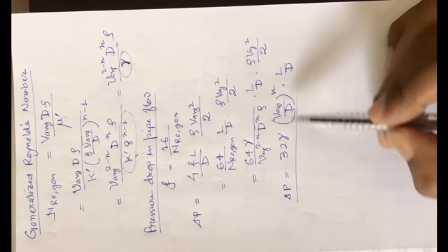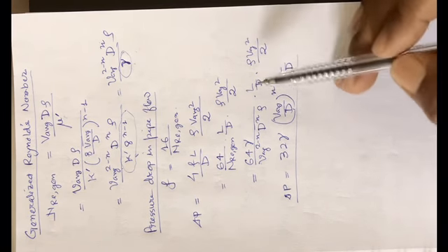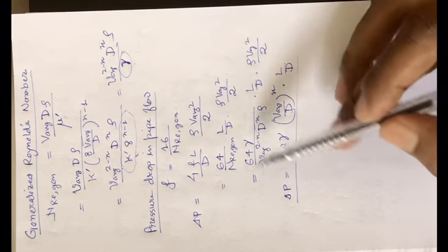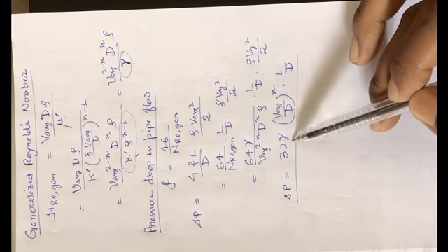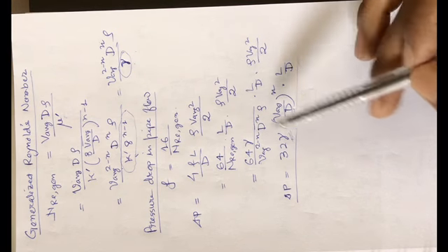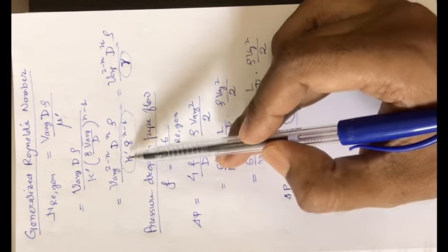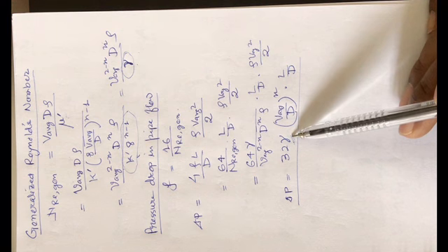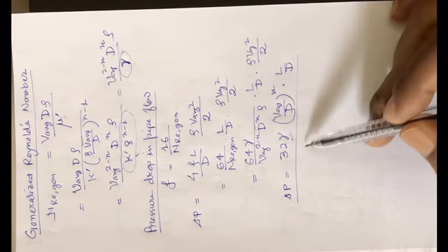Now somebody may simplify it by cancelling out the terms. Then it becomes 32 into this generalized coefficient of viscosity. But again, you see, the generalized coefficient of viscosity has this expression: K prime into 8 to the power n minus 1. So it is 32 into the generalized coefficient of viscosity, V average by D to the power n, and into L by D. So this is the pressure drop.